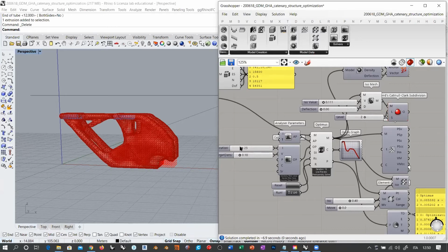Also, in general, iteration number 25, that we are going to reach quite soon, more or less, is going to be worse than iteration 50. So if you have the time, I do recommend that you leave these topological optimization processes running, especially if you have some time out from work or so on. You leave the computer calculating and then see what's the final result. So don't stop the optimization process, because some things happen only with high values of iterations.